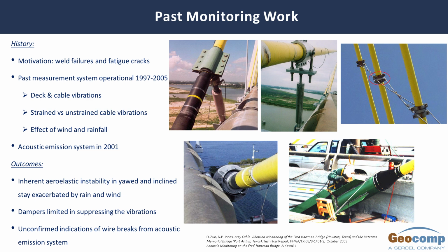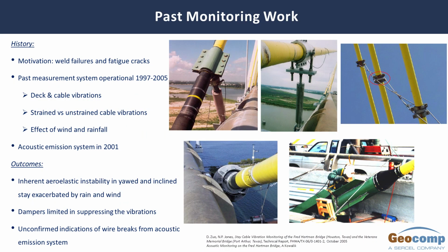There were several accelerometers installed on this bridge, and there was a study out of this 8-year data collected in terms of the dynamic performance of the bridge, especially in the context of adding dampers on the cables, before and after. Following some cracks or high vibration problems on the cables, there was a need to look at the data and do some mitigation work by adding dampers, and to understand if the addition of dampers solved the problem, or what the current condition or baseline of the bridge is. That was the idea.